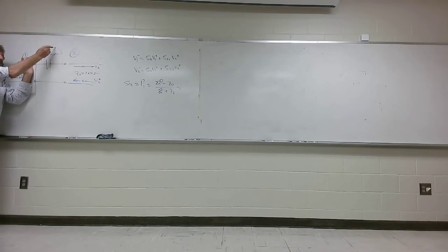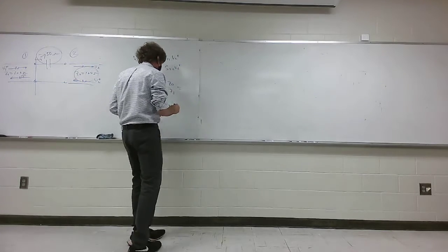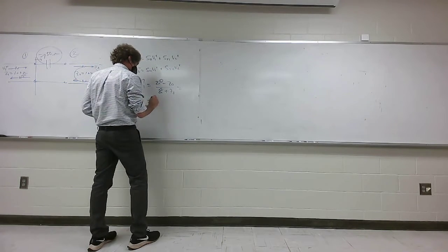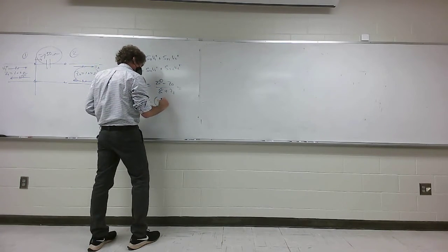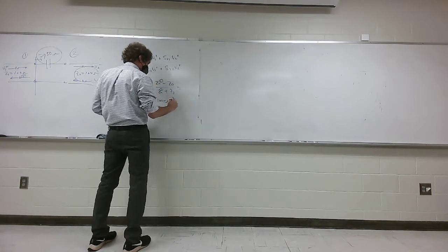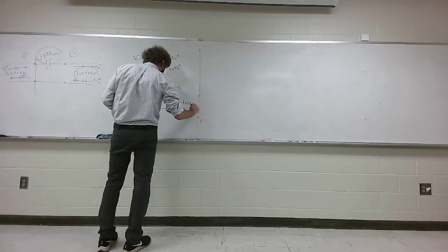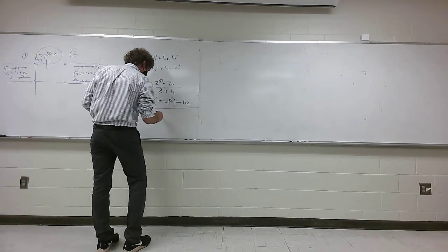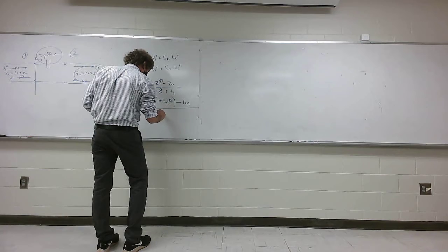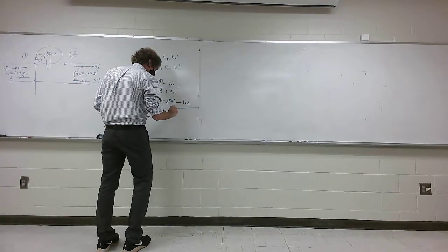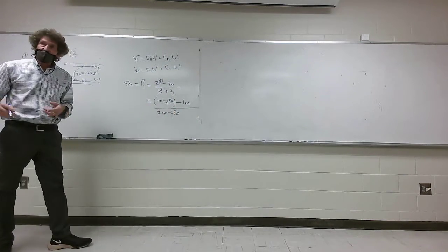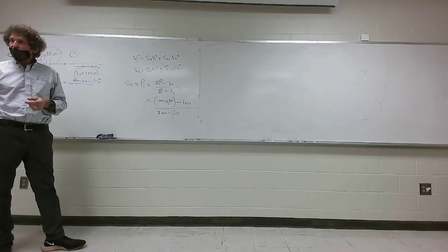I'm looking here, right? I'm going to have this in series, minus j50 with this 100 minus j50. Correct, class? So this would be equal to 100 minus j50, minus the characteristic impedance, 100, over the sum of those, or 200 minus j50. Y'all with me? I'm just doing the math here as simply as I can. Agreed, everyone?